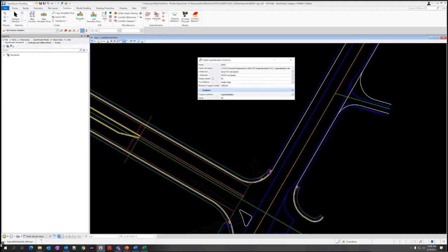Now it changes again, this dialog. Now that it loaded the XML file, it has all these settings. Again, it's not going to prompt you for these settings, so don't just accept. Do not accept yet. So you want to change all these settings here to make sure it matches your file and how you want it. So for the Emax, this is a low-speed roadway, so it's 5%. The L selection, it's basically we got low speed.